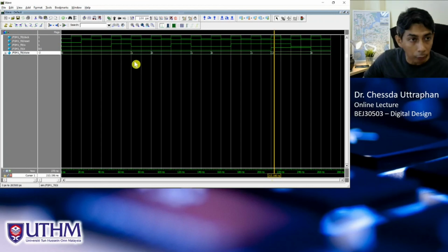Because it will delay one cycle for Z. It will go to the next state when W equals 1 here, go to state B, and 1 here means B. But because for the next one W equals 0 here, it will go back to state A here. 0 here means A, right? And 1 again, and only one measurement. The next one is 0, so it will go to B, but the output is still 0. And the next is go to A already, right?